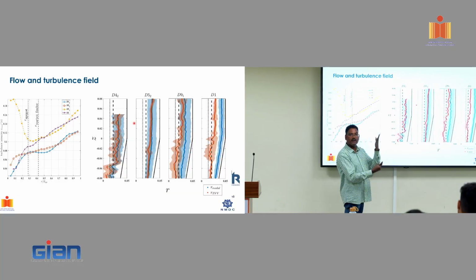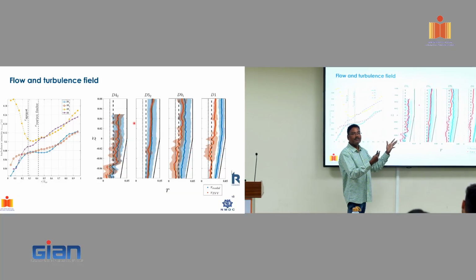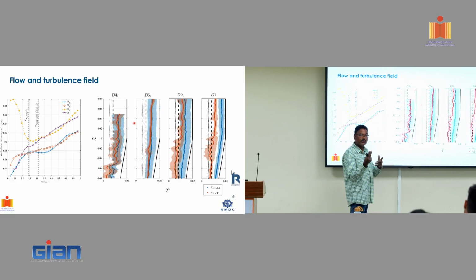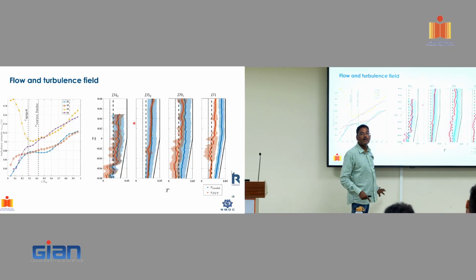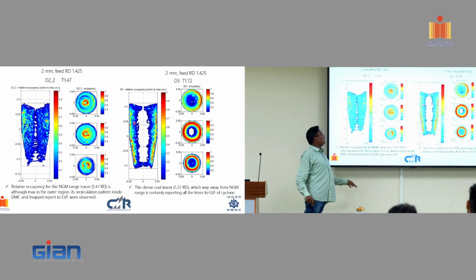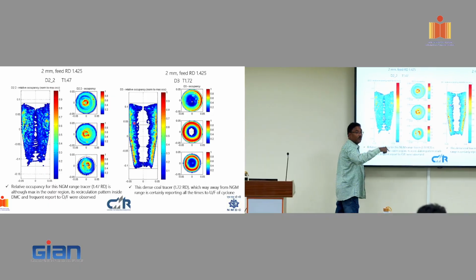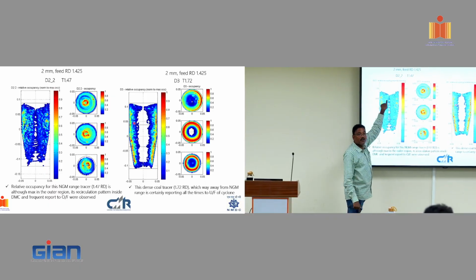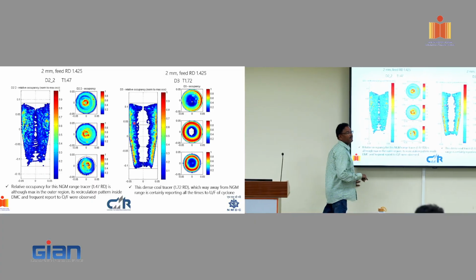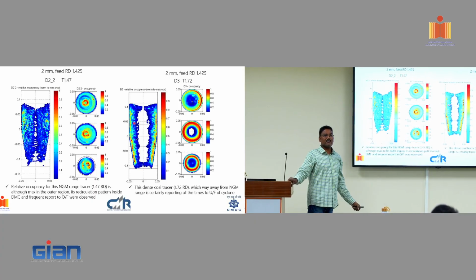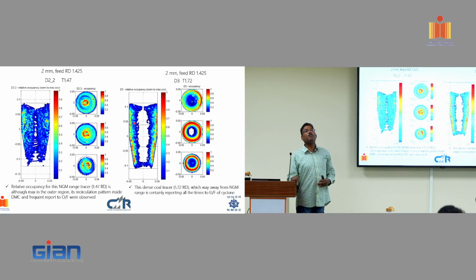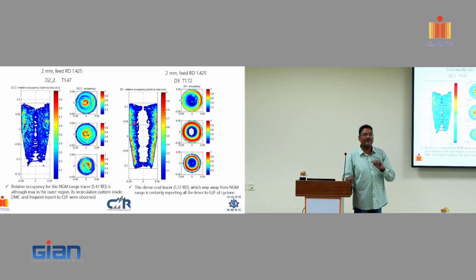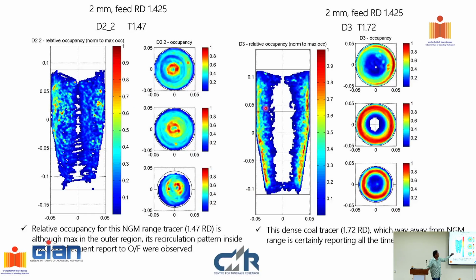That is under stationary gravity. Now, if it is centrifugal acceleration, maybe 50 to 100 times or even higher, it still shows that behavior within the radial range. So we see that random behavior of those particles. If I look at it in a vertical plane, you see these particles are getting recirculated. That's the first time evidence we found. In fact, it was always speculated that circulations would happen. Our question is how long that circulation would last: is it for 1 second or a millisecond? That is what we aimed to target, and we attempted it that way.